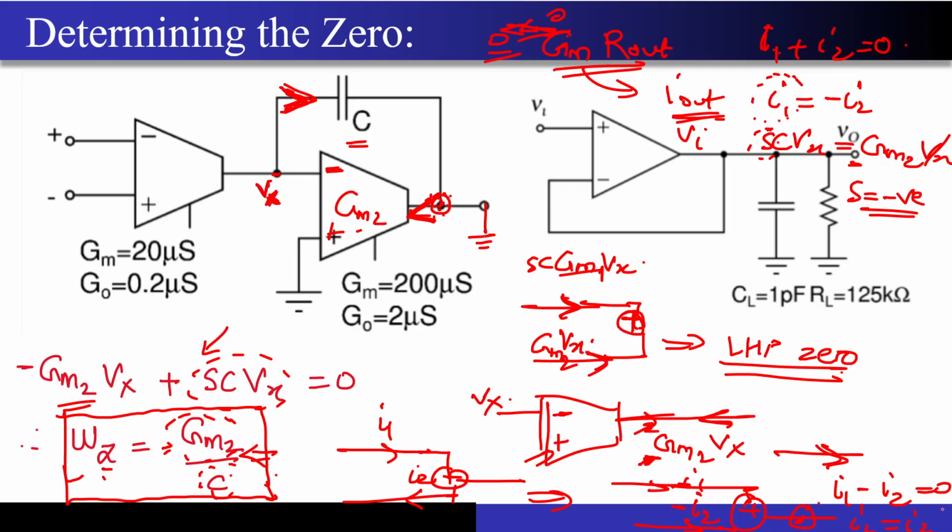So now this came what? I1 equal to I2. Now even if one of it has this particular term SC times Vx, there is no negative sign that you will get in this particular expression which can make the 0 occur in the left half plane, correct? The left half plane means the S equal to negative, correct? Remember your 4 quadrants, correct? This is the S that we are talking about, correct? If your S occurs somewhere here, then you know that your S is negative, correct?